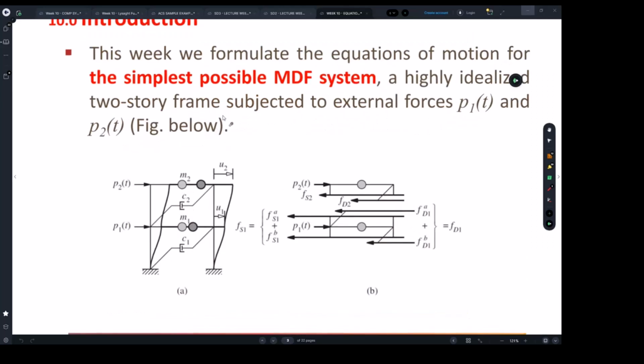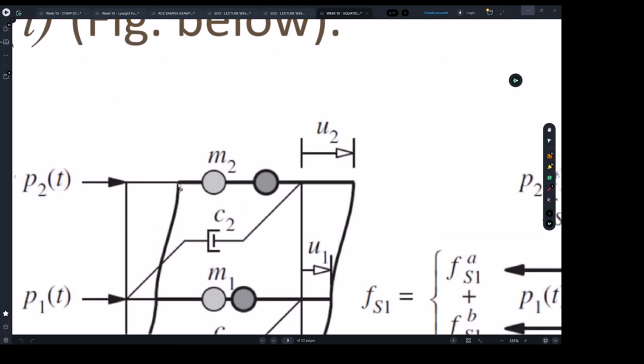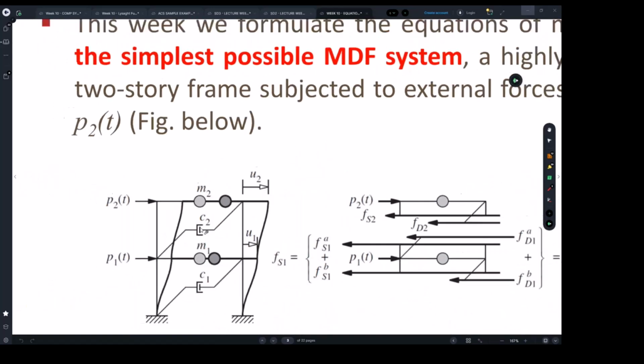As I said, with heavy loads, the columns, especially at the lower levels, are going to get shortened, right? And that shortening will require us to make some adjustments to the equations and theories we're developing. Not only that, sometimes the rotations at these corners will be significant to consider.